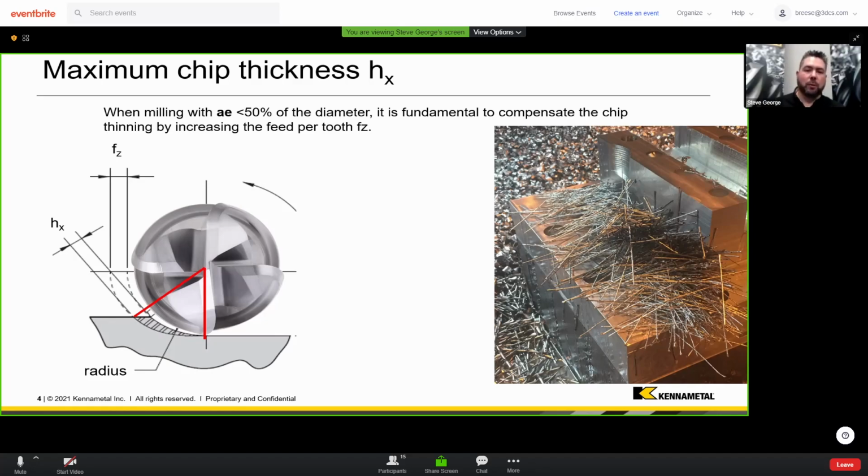So when you get into high-speed cutting and then turn that into high-efficiency milling, again, what I'm talking about together in terms of dynamic techniques is this: we are designing these cutting tools, be this a solid or an indexable, we're designing that edge to be able to take a certain maximum chip thickness. So the first thing is to max that out. That's rule number one. And there are some good reasons why I would want to max that out. The main thing is productivity.